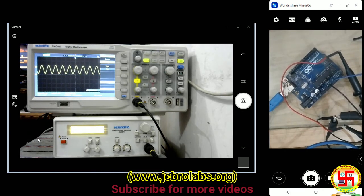Okay, so now because we have connected the leads of this function generator and DSO together, we were able to show you the waveform. Now we will do a simple test, because our first task, remember, is to obtain the sampling frequency from this Arduino. We want to know what exactly sampling frequency we are getting. So we will write a program in Arduino which will sample some data, and then we will toggle the built-in LED at pin number 13, and we will see the waveform coming at this pin number 13. From there we can understand what sampling frequency is available to us from this Arduino. Okay, so let's go to the Arduino now.